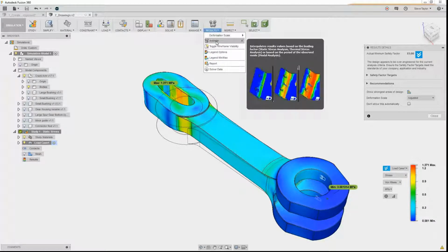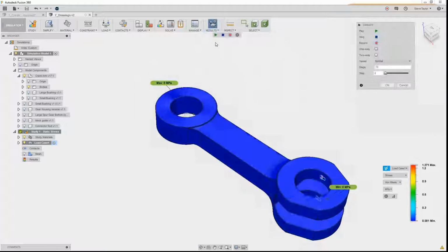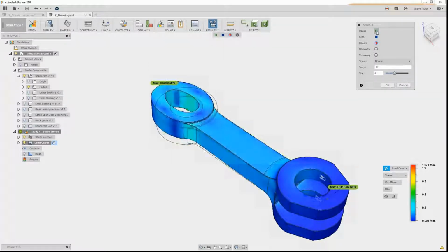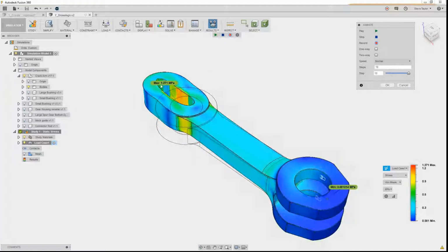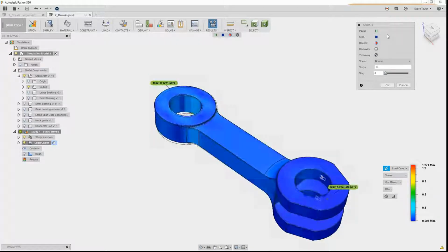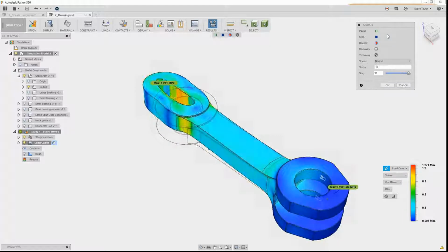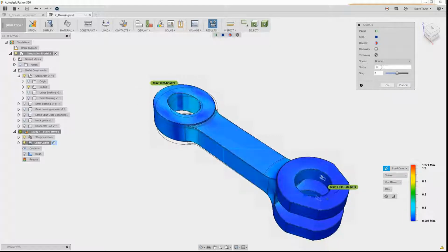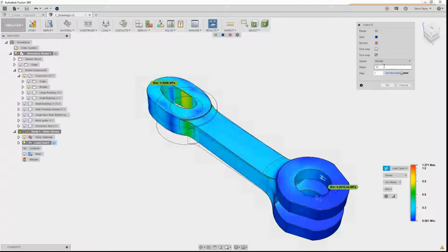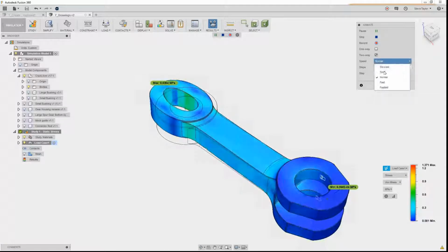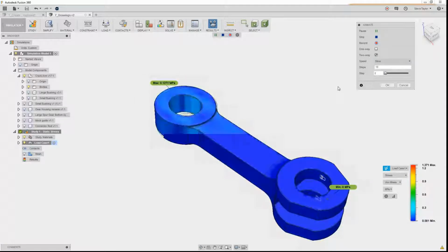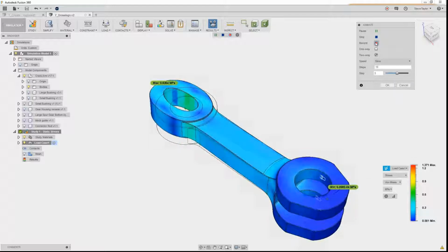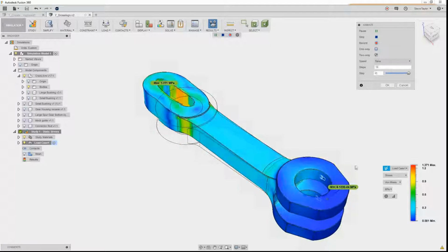One thing that it does do, which I quite like, up at the top with the results, you can actually animate them. You've got the option here to play in number of steps. Again, this is really exaggerated. You can stop, you can record it, you can have it two-way, so it goes backwards and forwards. You can change the number of steps. This is initially doing 10 steps. You can change that. You can change the speed, so you can change it to slowly. You can record it.